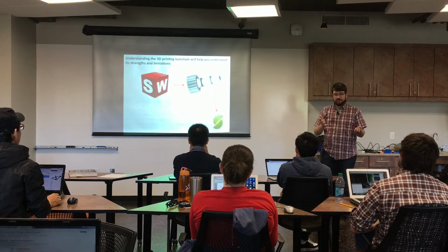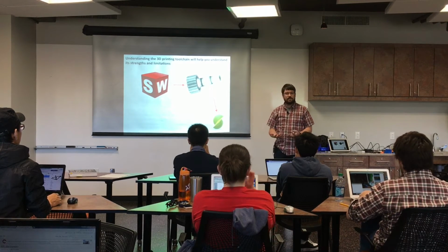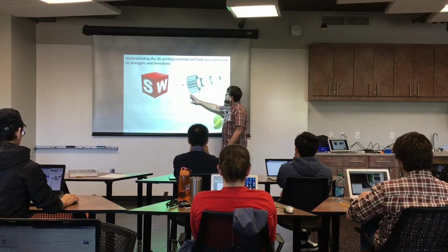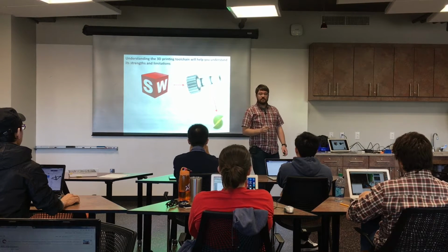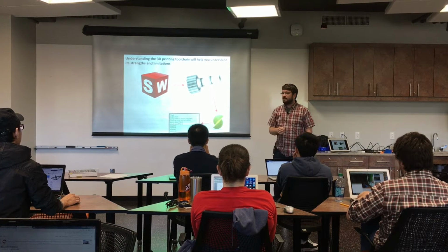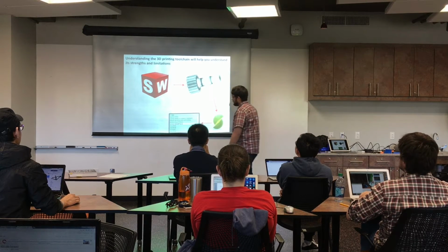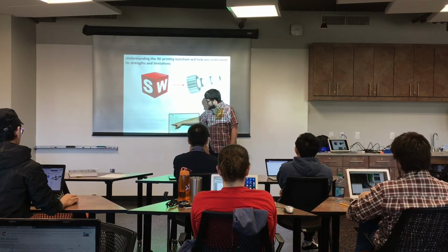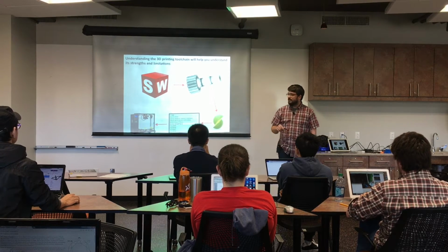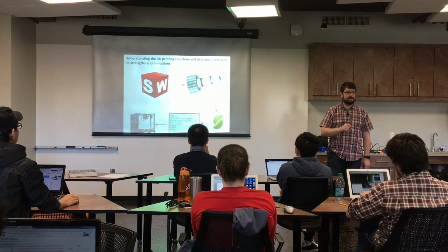Then you take this STL file and you take it to a program that's called a slicer. This is the equivalent of a CAM piece of software for the machines that we saw when we went over to Ellis's shop. What the slicer does is it goes through and actually generates how the machine is going to make the part, what tool paths are going to be used. And it saves that out as a file called a G-code file, which Ellis talked about some as well. It's called G-code because you can see there's G and then a code and then some positioning commands here. And then that G-code file is fed to the 3D printer, and that's what actually creates the print.